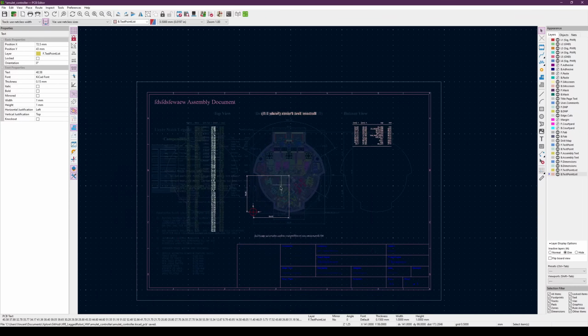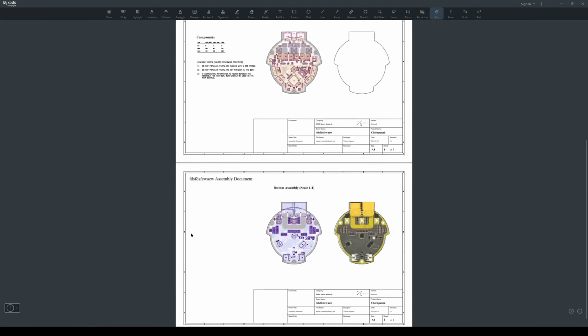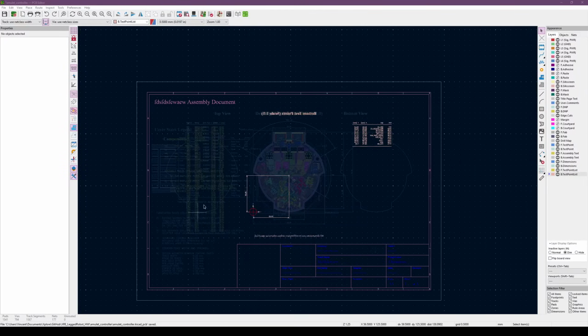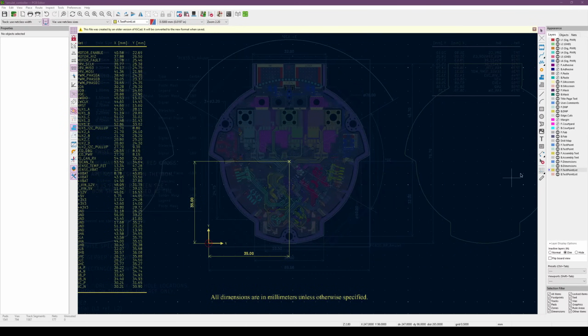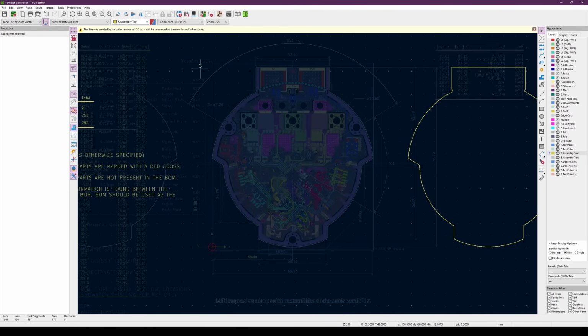And after this, you are actually done with all of the things to fill in order to generate these types of documents. Of course, you will just need to make sure to revert the footprints of the test points before generating the position file or the centroid file that you will give to the manufacturer. Once you've finished adding all of the necessary data in all of these layers, you can start generating the documents.